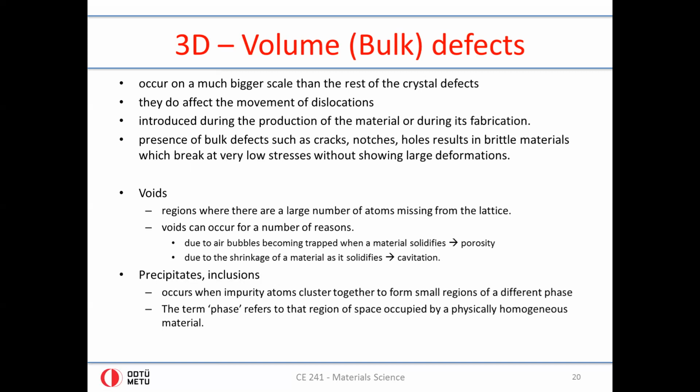So because of this, when you have a large crack or a void or a problem in your crystal or in your overall material, you will have a significant influence on overall properties. And if you ask, what size impurities does a civil engineer need to care most about? The answer is volume defects. And the reason for this is because they are very large.